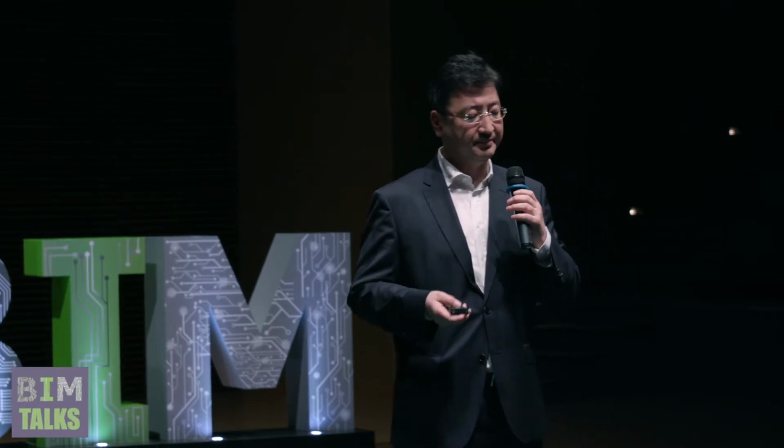Also, we have to consider up-to-date information about ground conditions at multiple points in time, because as excavation progresses, we can gather more information about ground conditions by using face mapping, probe drilling, or something like tunnel seismic prediction.